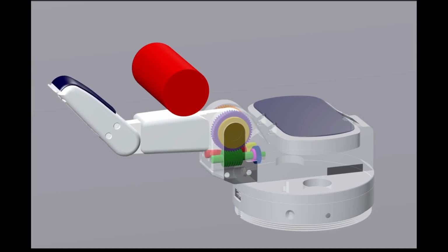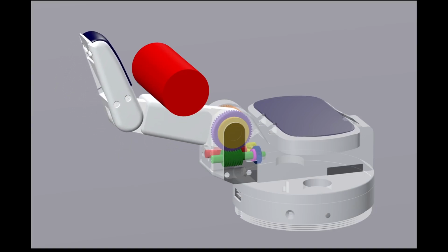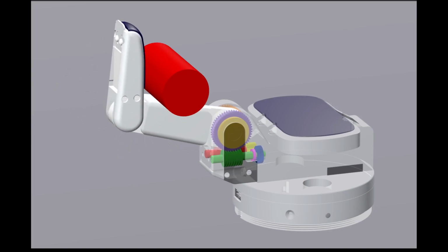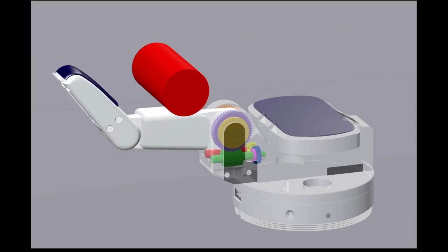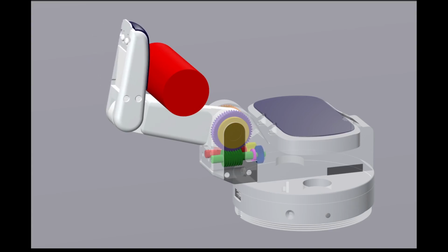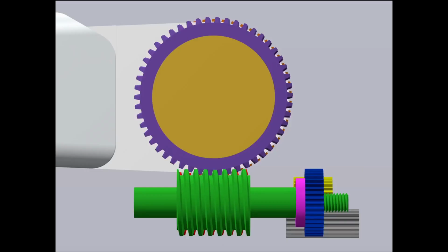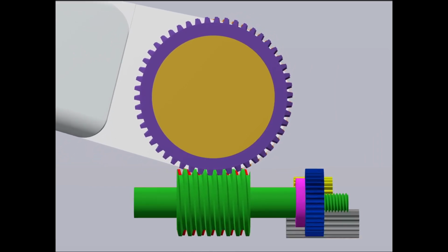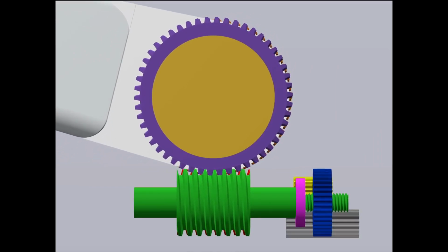The predictive capabilities of the method are demonstrated by simulating the unique gearing mechanism of the Barrett hand, which relies heavily on friction and stick-slip transitions. In this system, a single motor drives both the proximal and distal links of a finger through a coupled gear arrangement. The proximal gear rides freely on internal threads along the shaft of the adjacent worm gear, with Belleville washers at the end acting as a clutch.